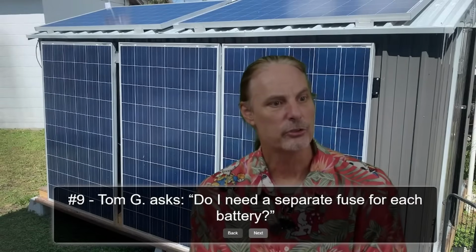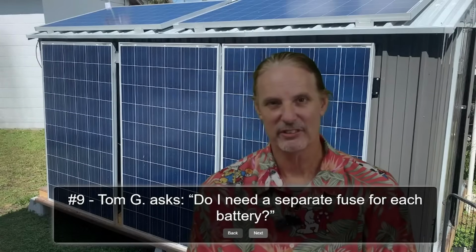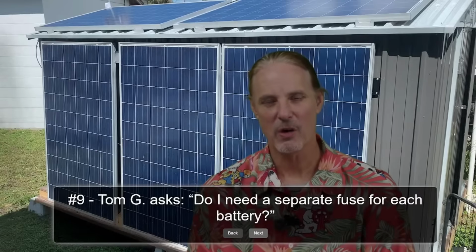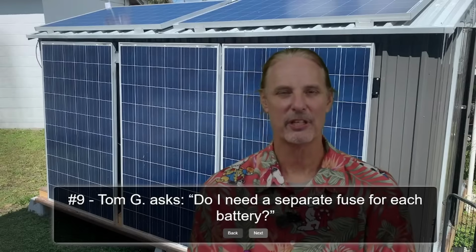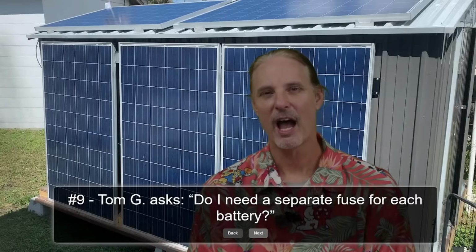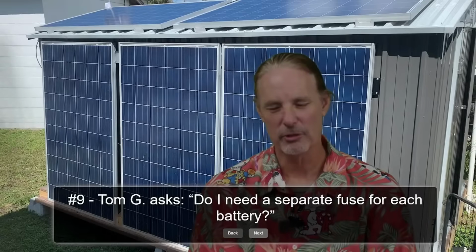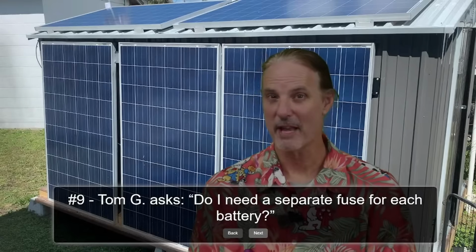Tom G asks, do I need a separate fuse for each battery? This is very much like asking this question about solar panels and do I need a fuse for every solar panel? And technically the answer is no. In my mind, batteries are different. And yes, some batteries can absorb the power between 200 amp hour batteries, and connecting them don't have that problem. I would suggest that yes, you should have a fuse for every battery, because it is extremely, extremely important in a safety matter to stop the battery from being discharged in a manner that you don't want it to be.